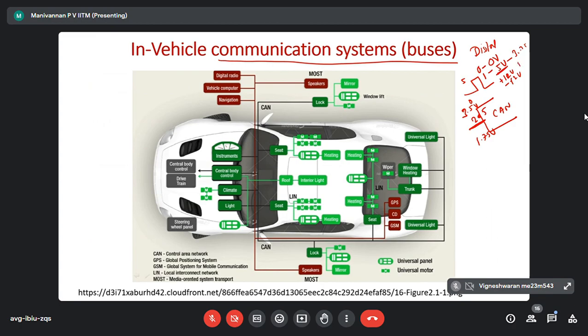Right? 1 is represented by one value, 0 by another. When you say binary 0, I am talking about a binary value, and that is represented as a voltage. In an electrical system, only voltage can represent the value. So in CAN bus, it is 2.75 to 3.5 volts. One represents binary 0, the other is binary 1. In some other communication systems, it is 0 volts or 5 volts: 0 represents 0, 1 represents 5 volts.